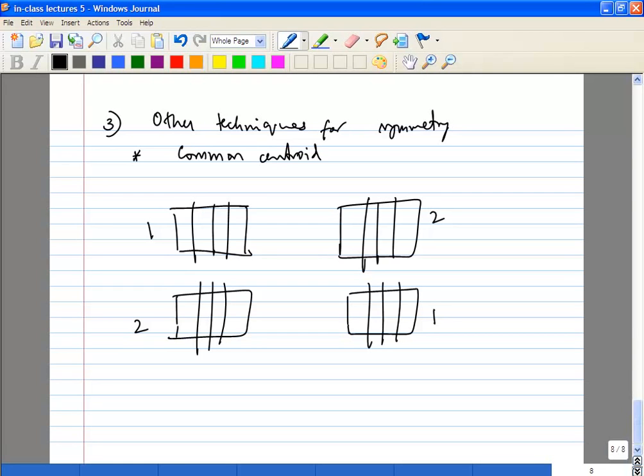It's quite common. Now the only thing you have to be very careful about is this is very layout intensive, because let's say you had to connect out these gates. Now you have to route the gates, and you have to route the source and drain connections. So it's actually very intensive. And I would say in RF layouts, it's only of limited value. But like I said, there's always an exception. You may find a case where you might want to use it. So let's call this A.